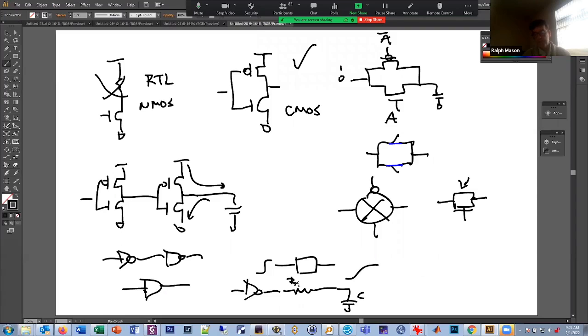It'll slow it down. So the transmission gates we're going to see are very effective at generating logic, but it's got a drawback, particularly if you put a bunch of transmission gates in series like this. Oh, it gets terrible. You really can't do that. If you put more than one, you start getting all these RCs, and then this node up here starts looking bad. It's slow. We're the picosecond generation, or you are. You will quickly become nanosecond people if you do something like this, okay?